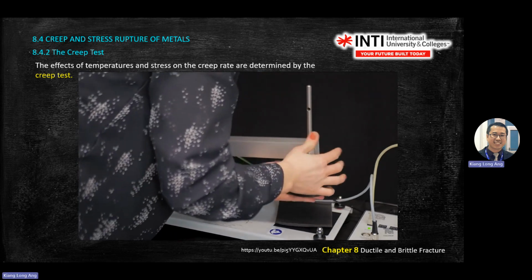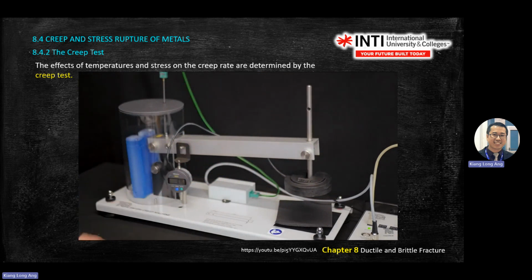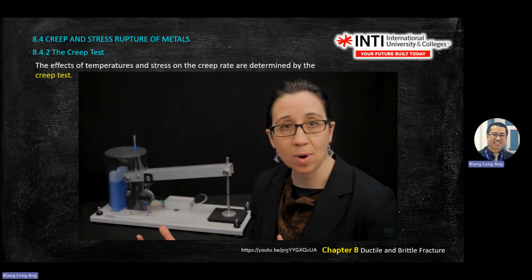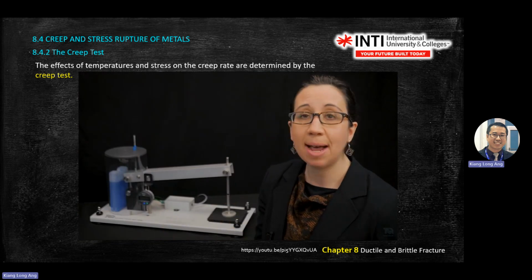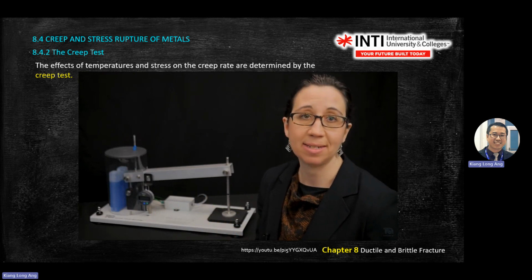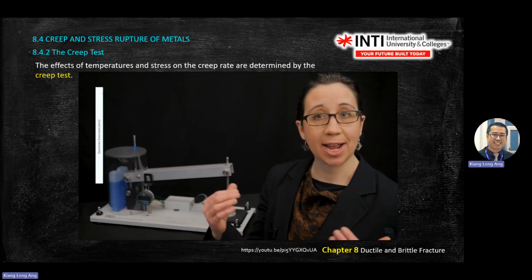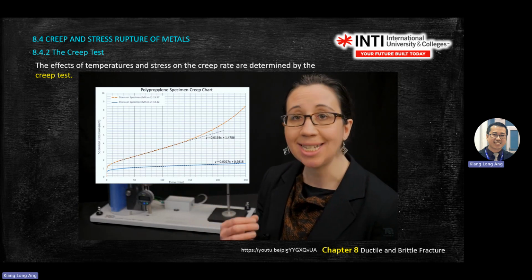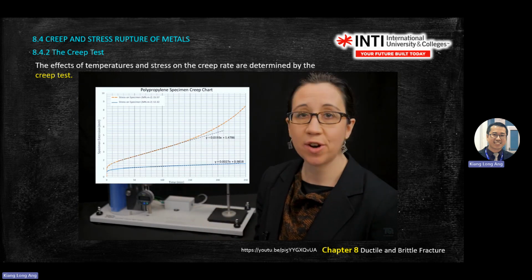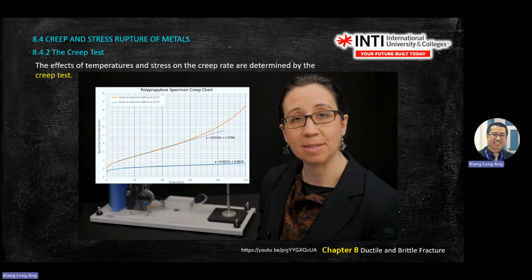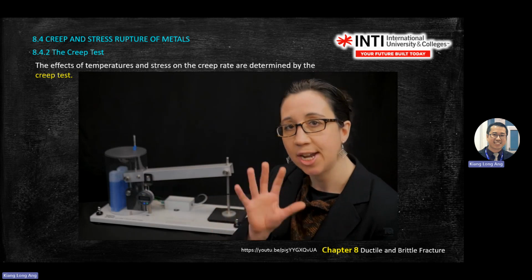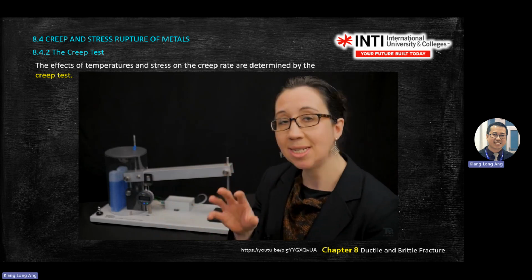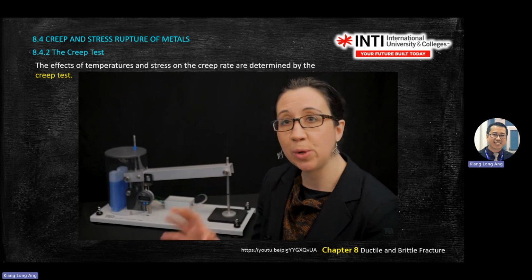For some materials, this is going to take hours, which is where VDAS really becomes very useful. Go through all of these specimens with different weights and then repeat using the cool pack, both cooled and heated, to examine the impacts of heat on the specimens. When done, you can create a chart of specimen extension against time and calculate the curve gradient to establish the creep rate. Another experiment in the user guide takes you through elastic extension and creep recovery in plastics, testing the polypropylene specimen at room temperature.